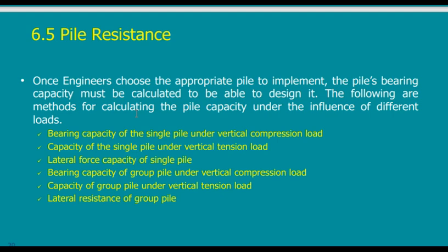Usually it would have many piles below it. So if I design a pile, I will design one pile. Then I should check what this one pile will do if it works in a group. We are going to discuss this very quickly now.